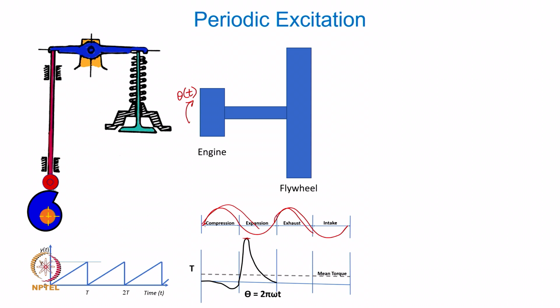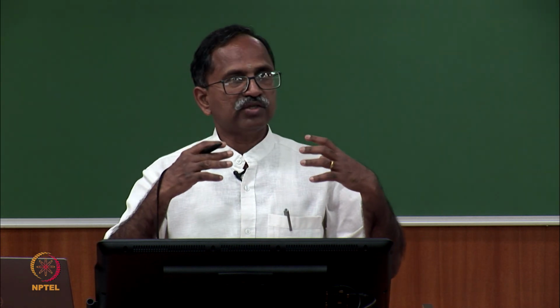That is the whole purpose of our vibration analysis: given certain speed and operating conditions and the torque being generated at the engine, what is the maximum twist the crankshaft is going to be subjected to, and, assuming that this vehicle is going to work for 10, 15, 20 years, is that going to create a fatigue failure in the crankshaft.